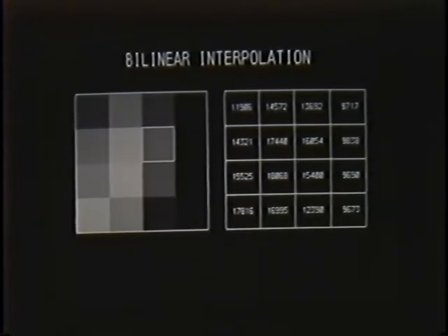If a real image is shifted to the left, that means that the sensor moved to the right. In this case, the sensor, which is currently seeing the shoreline in our selected pixel, would see more water and less land after a quarter pixel shift. We would expect then that the pixel would become darker and that its numeric value, now 16,054, would become something less. The pixel to the right of this pixel, which has a value of 9,838, will also play a part in the interpolation.